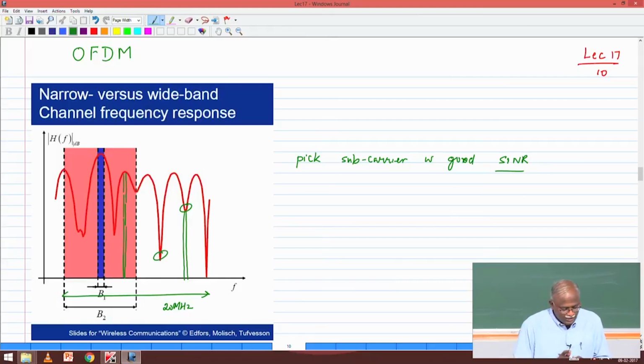Okay? So this is to answer the question, is frequency hopping only for narrowband systems? The answer is yes. It is for narrowband systems, single carrier. For narrowband systems, multi-carrier, you just avoid using those bad channels. If it is a single carrier wideband system like CDMA, then you have time resolvability, you take advantage of the multipath and therefore are able to get a good performance in the channel.